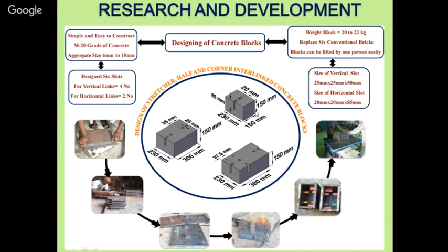After that we have prepared this corner block. This corner block is a little bit bigger in size. It will work as a through stone for the corners. That's why we have developed this corner block, so that the corner does not split. The corner block size is a little bit bigger than that of the stretcher block.